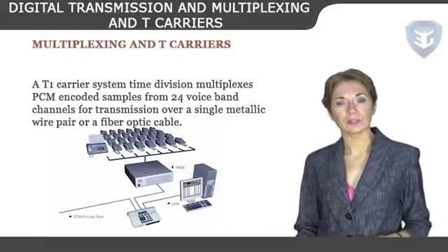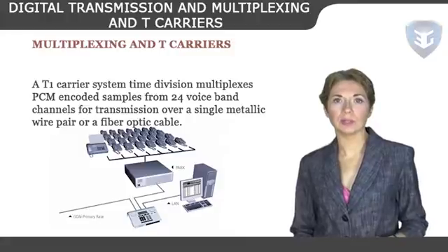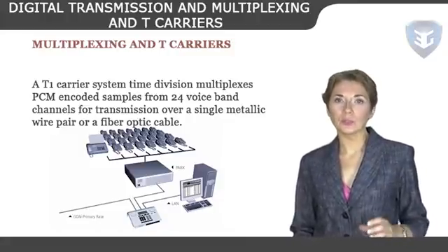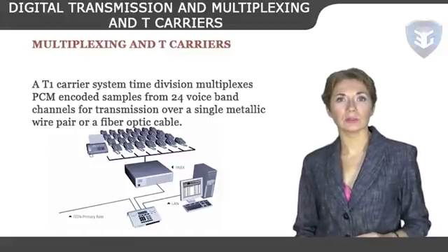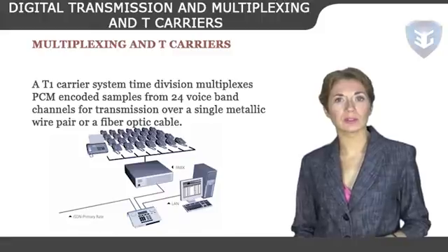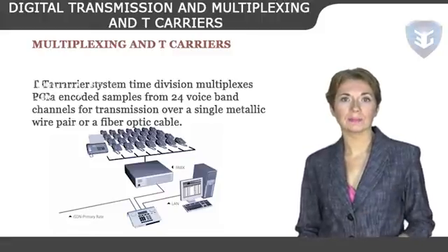The multiplexer has 24 independent inputs and one time division multiplexed output. The 24 PCM output signals are sequentially selected and connected through the multiplexer to the transmission line.